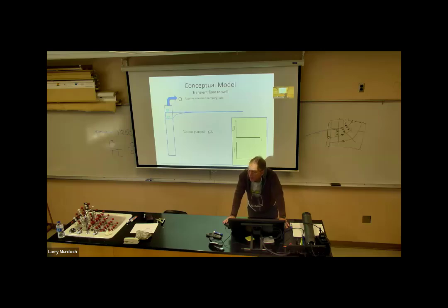We've removed it. So back when we were talking about storativity, we were saying, well, storativity is the volume of water released from storage per unit area per drop in head. And the reason we cast it in that framework is because of this.